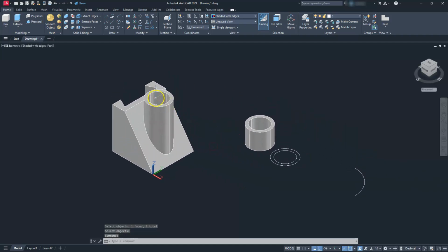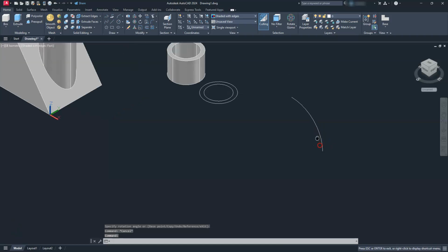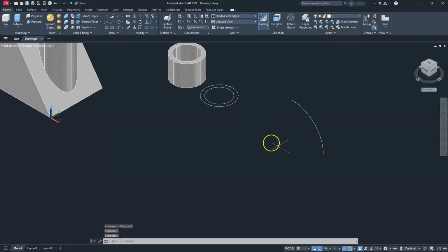All right. So this top piece of pipe I can't put in yet until I put in the elbow. The way I'm going to create that is go ahead and go back to my rotate gizmo. I'll select this arc that I have here. Let's go ahead and select the red axis and come straight up and do a left click. Go ahead and hit escape. And then I'll go ahead and zoom into this. I'm going to move these two circles to that endpoint. So I'm just going to highlight them. I'll pick this center grip and then I'll place it on this endpoint. All right.